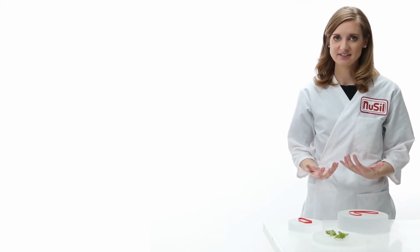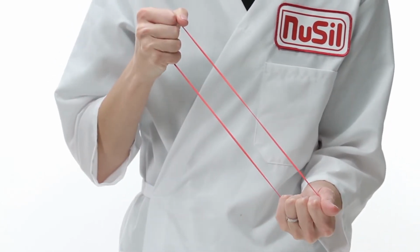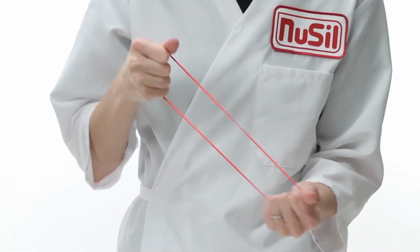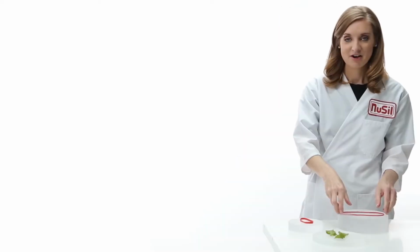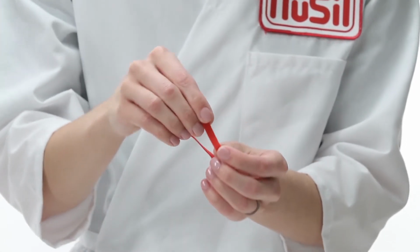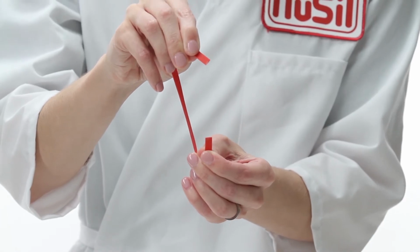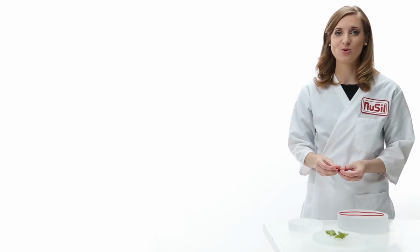In contrast, let's think of this rubber band. I can stretch it without breaking it, so we would say it has high tensile. And since it stretches far without breaking, it has high elongation. Finally, to simulate wear and tear, we've nicked this rubber band. Then we pull it until it breaks. The ease at which it tore is the tear strength, and since this rubber band tore relatively easily, we would say it has low tear strength.